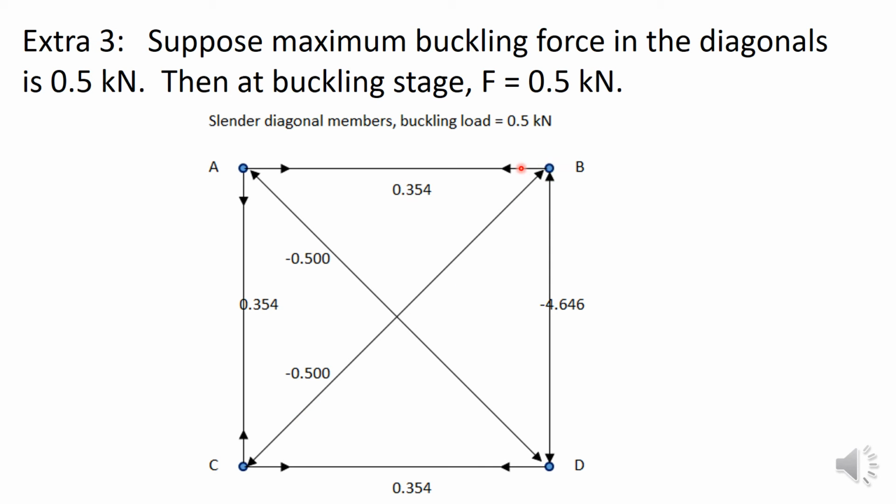Once you know the elongation of the members for these forces, you can calculate the distance B would move to the right or to the left, within which there is still equilibrium possible, and you can decide whether those displacements for B are allowable in some sense of the word.